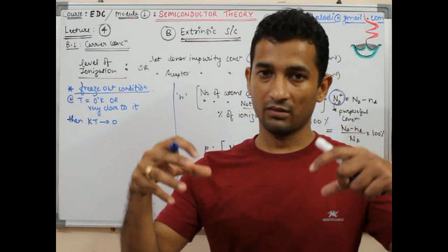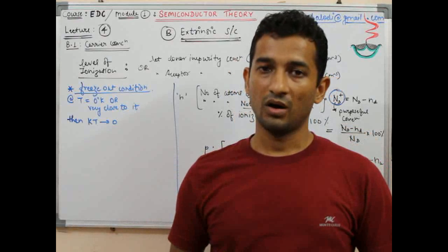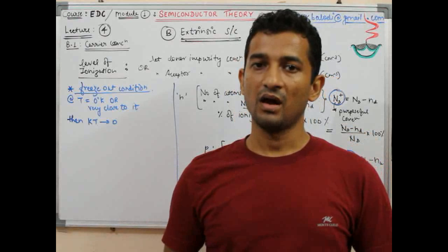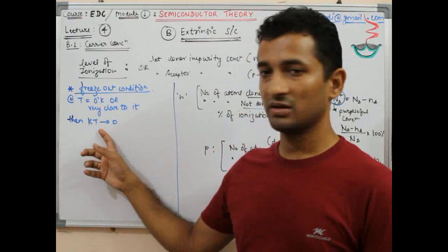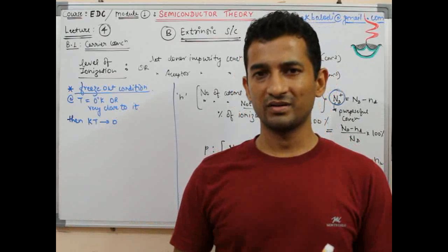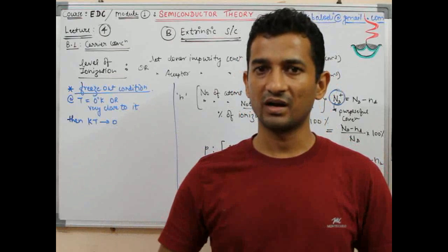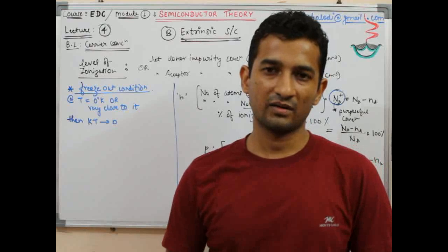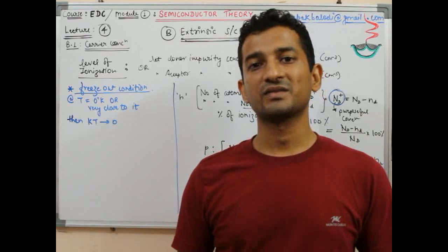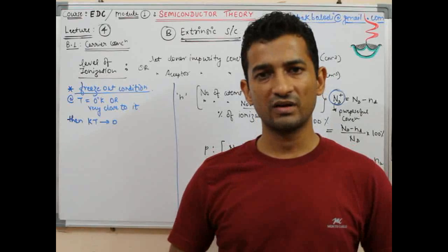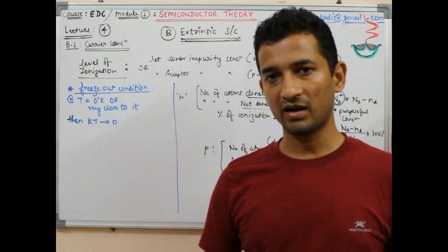So whatever atoms have been inserted as an impurity into the silicon are not able to provide their one electron or one hole, because the thermal energy is not sufficient to knock them out. Though it appears very contradictory or hypothetical, because when you are trying to insert something inside, the process itself cannot happen at freeze out condition, it is only hypothetical, just to make a reference point: suppose the temperature is almost zero and we are still capable of carrying out diffusion or ion implantation.